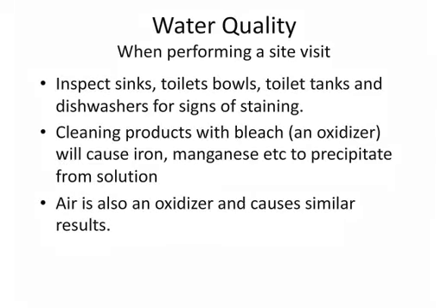Water quality, probably the biggest area that guys neglect. Probably the biggest culprit of problems that we see out there is the water quality, and I'm telling you, this is paramount. When performing a site visit, you always want to inspect the sinks. Again, I'm assuming this is a retrofit application. The project is already built out. When I come into a home, I'm looking around to make sure, number one, that the home is a heat pump candidate. It's well insulated.